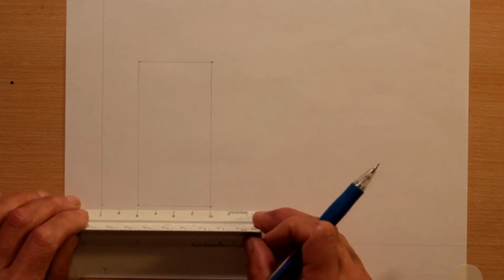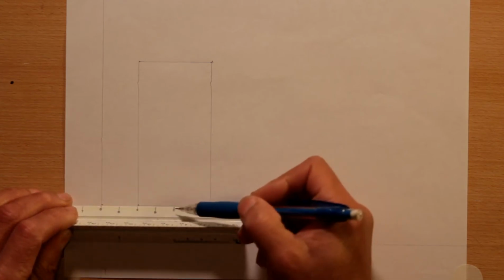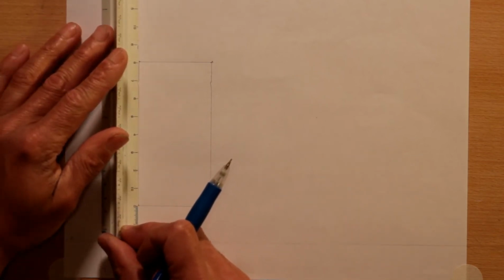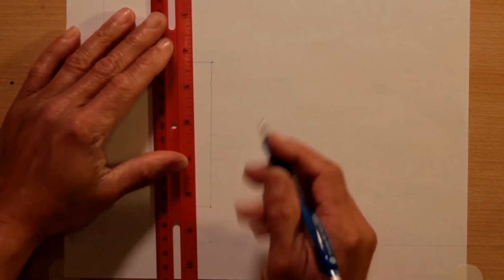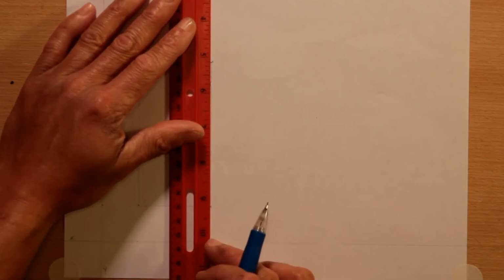You should have a rectangle that measures 4 foot wide by 8 feet tall. Now we add our extension and dimension lines. The extension lines are placed 1/8 of an inch away from the object. They are 1/2 inch long. Extension lines never touch the object, to avoid confusing them with the actual drawn object.